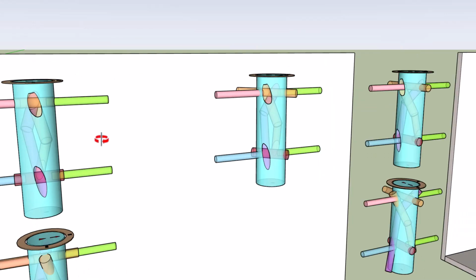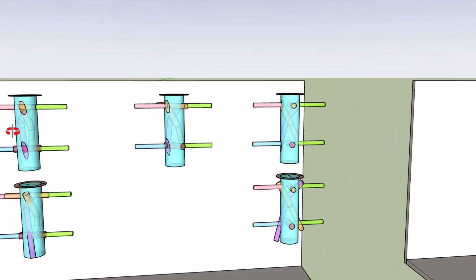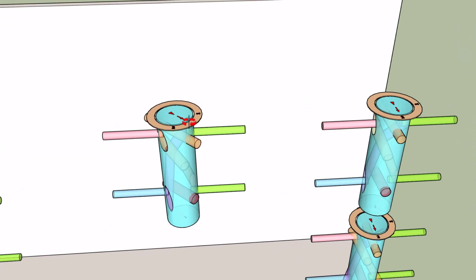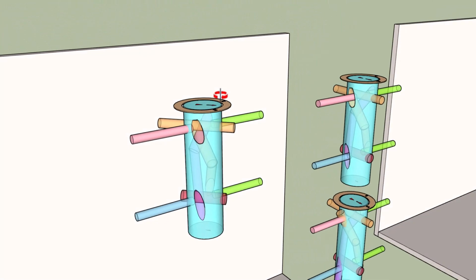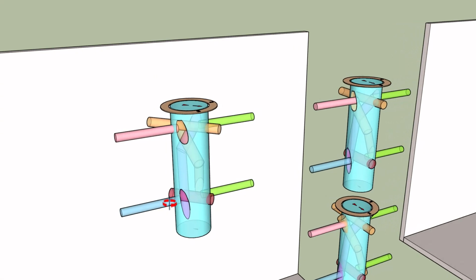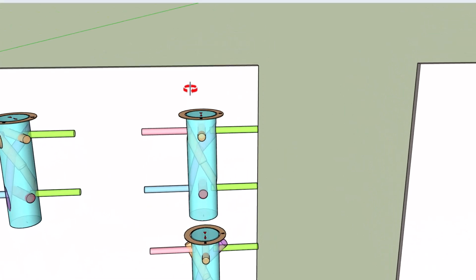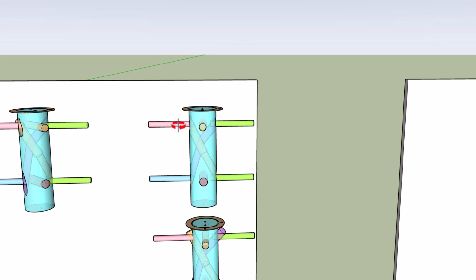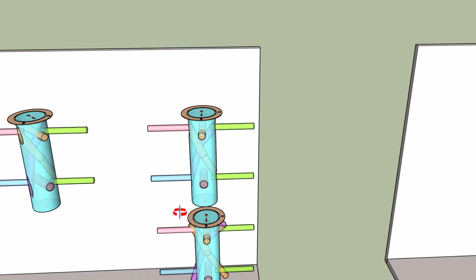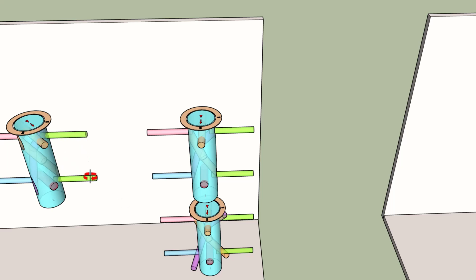And if you turn the valve, here the valve is in the off position, so the pressure is not connected to anything and the suction is not connected to anything. But if you continue to turn the valve to the number 2 position, the pressure now goes down here and the suction goes down here. And so the effect of this is, if this was controlling a hydraulic cylinder, in this position the hydraulic cylinder can't move. In this position, for example, the hydraulic cylinder would retract.